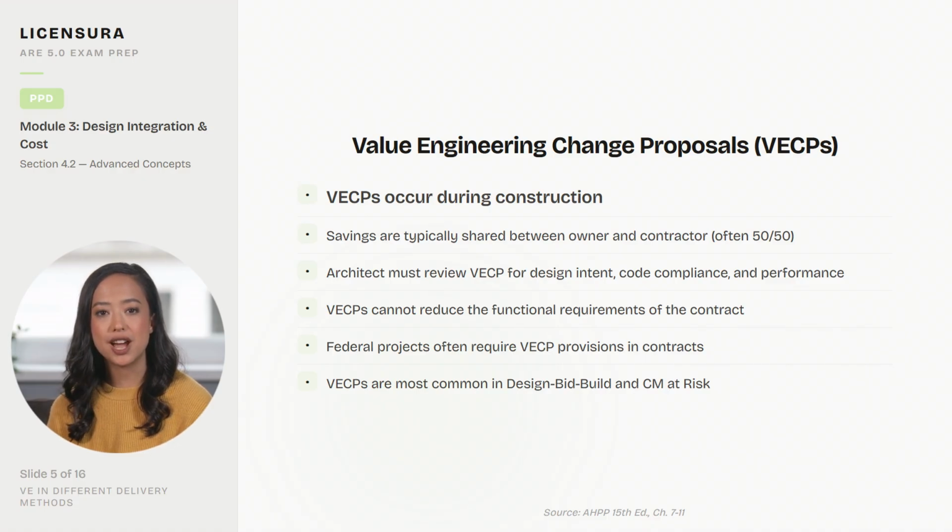Telecom rooms need 150 to 300 square feet per floor, stacked vertically. Ceiling plenums require 18 to 36 inches. Vertical chases consume 2 to 4% of floor area. Plumbing walls need 6 to 8 inches minimum, with wet rooms stacked vertically.